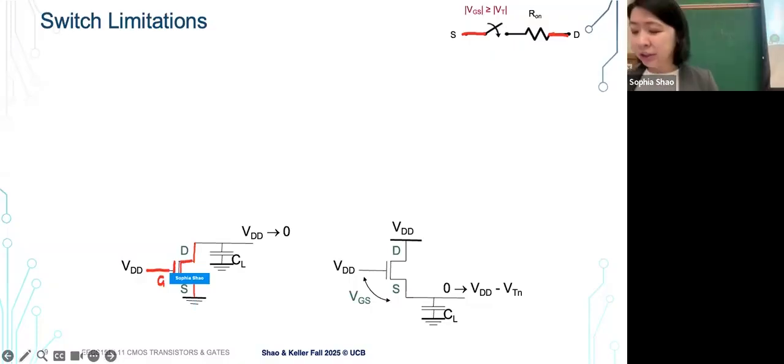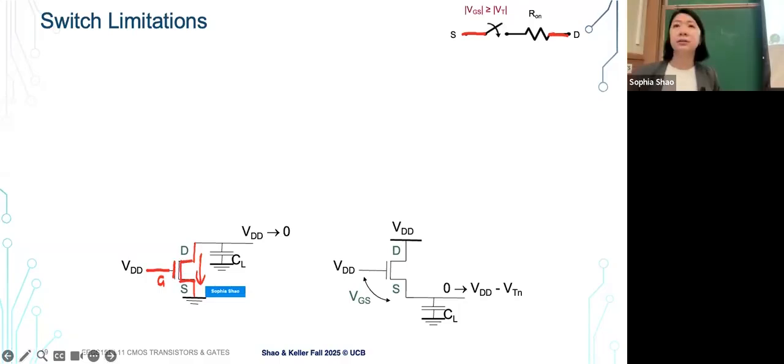When voltage is applied, the switch is on and current goes through. If we have a VDD at the gate, the gate is on, the current is there, and we can discharge the capacitor, so the output voltage gets to ground. This is a clean 0, perfectly discharged to the ground, and this is a behavior that we'd like to have, right?